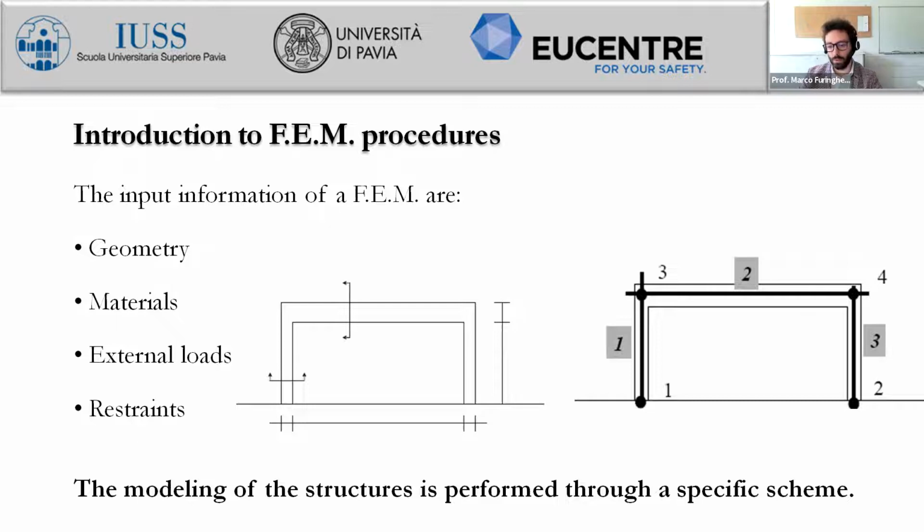So we have to use the actual centroidal line of a given frame rather than shells like the model I mentioned. So you have to model the actual flange and the web for a given profile, and so on.